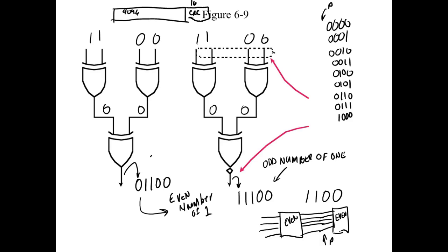So if I was gonna use parity, then every 8 bits or every byte would have a parity bit. So that means I'd have 512 bits using parity. Using 16-bit CRC, I send it in a block of 496 bits. Then I sacrifice 16 bits. So it's more efficient. So we're using less bits to get what? To get better accuracy.